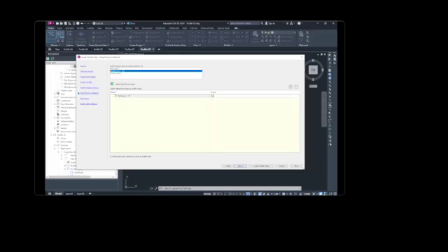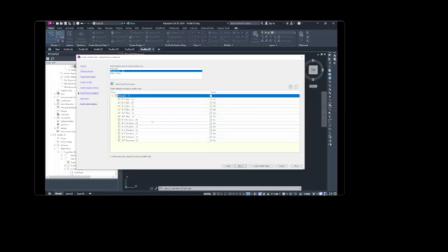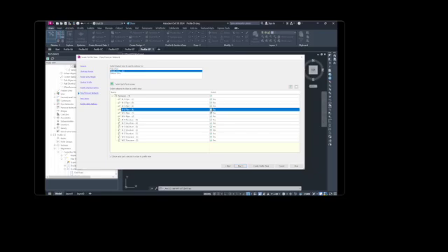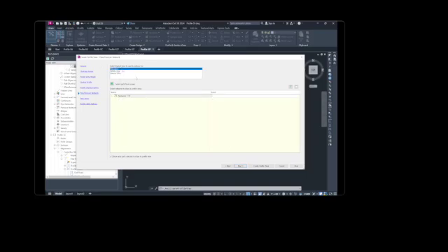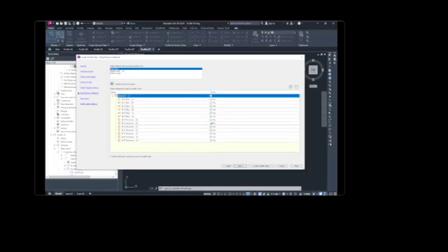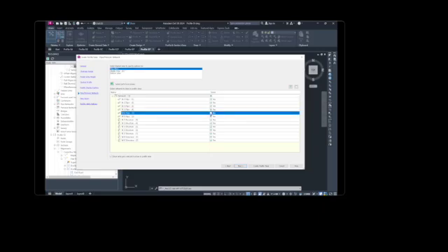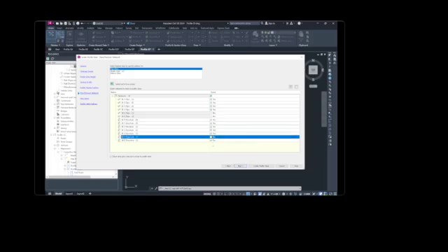For the middle view, check the box, expand the network, WE pipe 1, clear box, WE pipe 2, clear the box, WE structure 1 and WE structure 2, clear the boxes as well. And for the top view, check the box and expand, WE pipe 1, WE pipe 2, WE structure 1 and WE structure 2, all clear. Click create profile view.